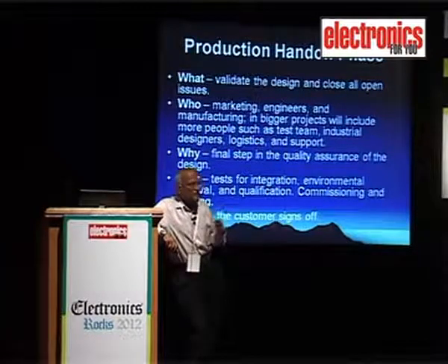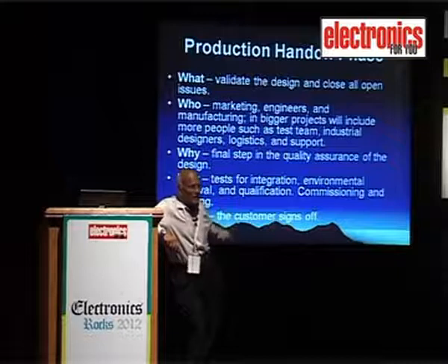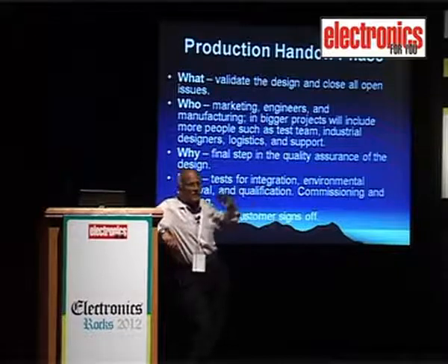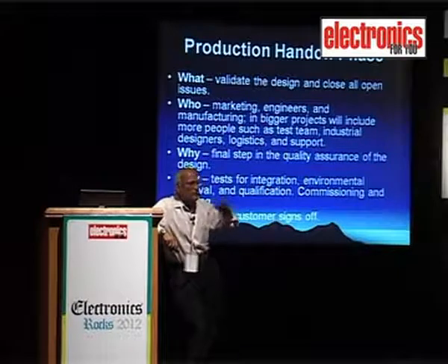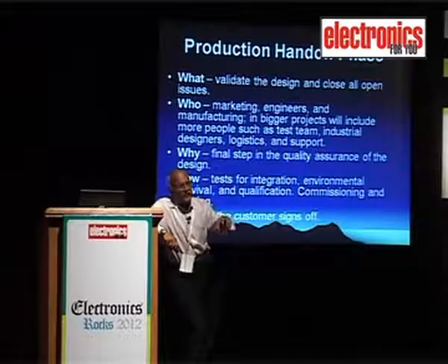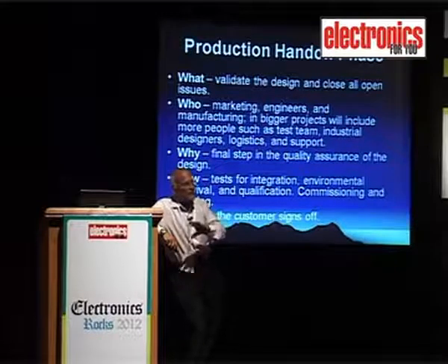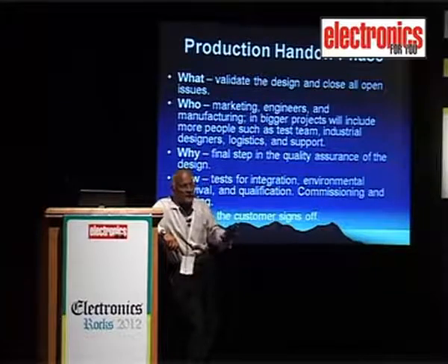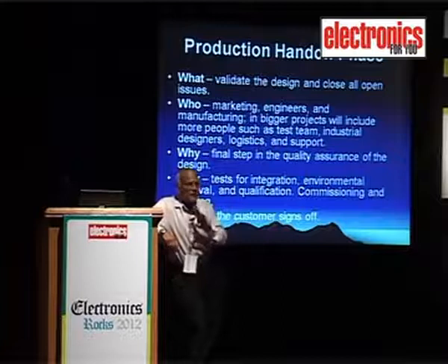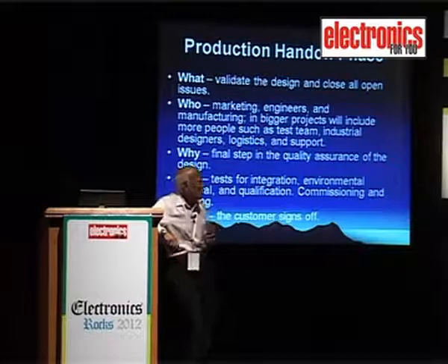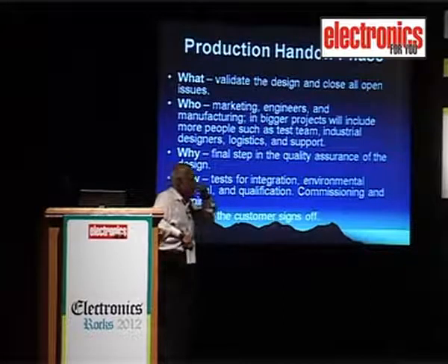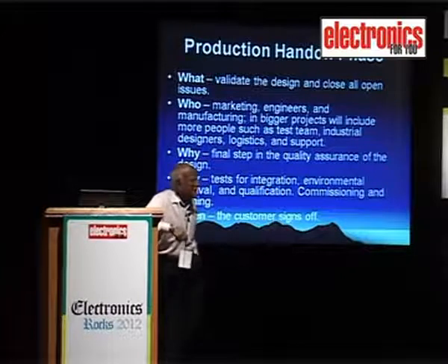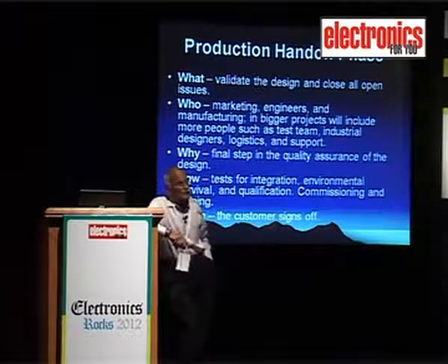Because you would change the conditions, you would have done some tests like what he talked about, the radiation test or EMI, EMC test. And the moment you change some values and put a new product inside, 2 years down the line, 3 years down the line, you don't get the same size of capacitor. The capacitor is either smaller or bigger. So you might have other issues coming into the picture, so you've got to be careful about that. So these are issues that we have to validate the design, close all open issues.